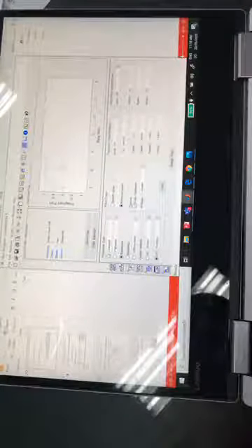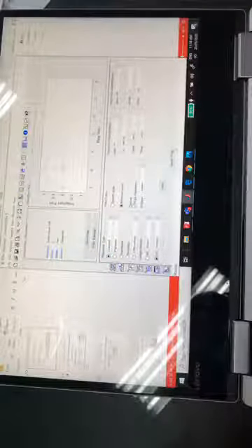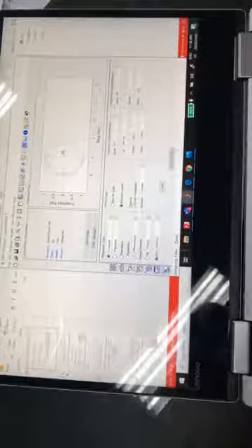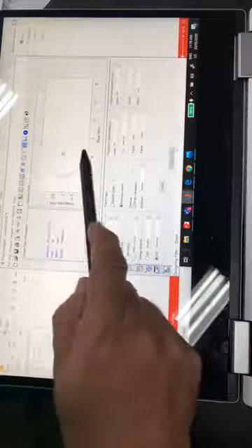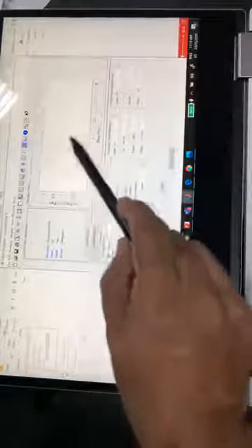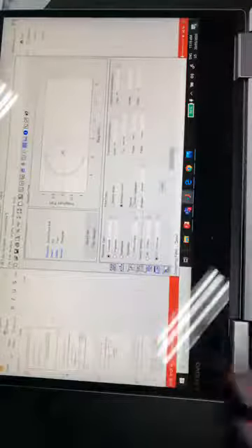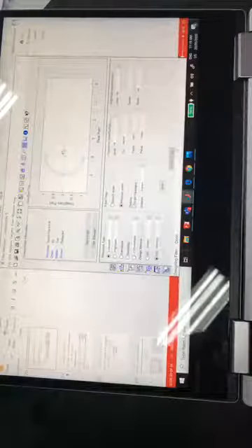So design a low pass filter with minimum order. Look, you see, it's a beautiful pattern. A cluster of 4, a 0 here, a 0 here, a 0 here. So for every 0, you see 4 zeros: 1, 2, 3, 4. 1, 2, 3, 4. 1, 2, 3. So they exist in clusters of 4. This is the frequency you are going to pass, and the zeros are placed. The filter design package has placed zeros on the unit circle. So M is 45, and a 0 is placed on pi as well.